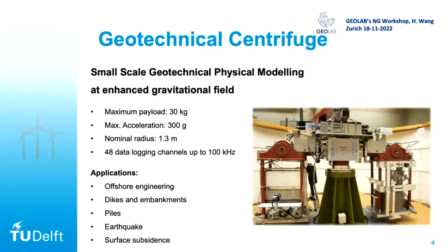And the good thing is we have a lot of logging channels. In total, we have 48, which is very important for centrifuge modeling because that basically controls how many sensors you can install and how much you can know from your test. And the centrifuge has been used in many applications like offshore engineering and dikes, piles, earthquake also, and surface subsidence like settlement.